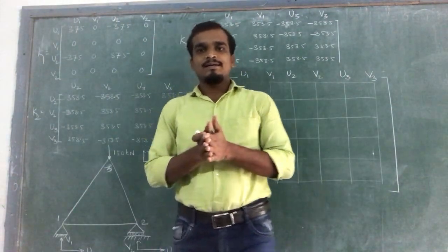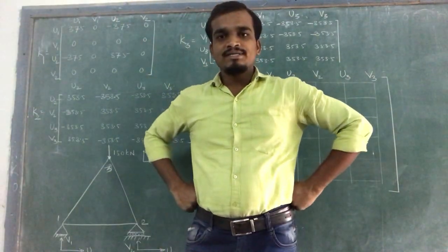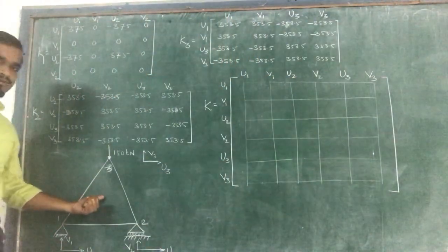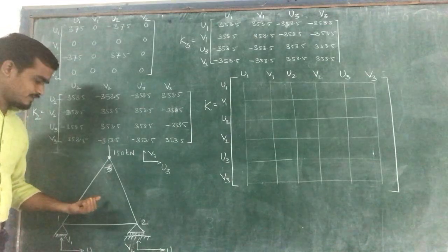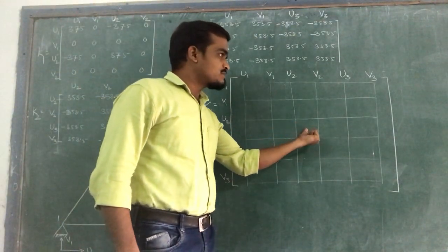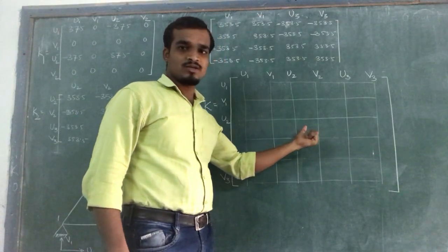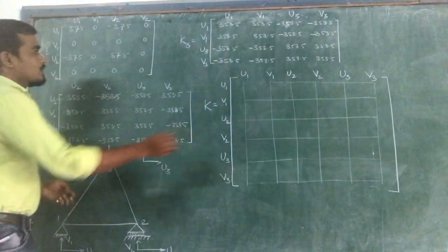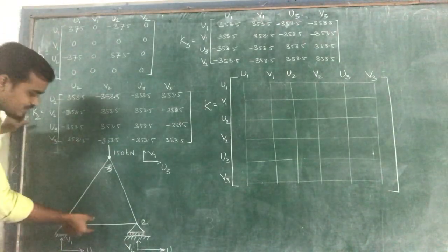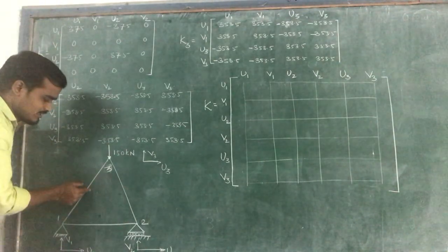Good morning, guys. In the previous lecture we started our truss problem. We started this problem in the previous lecture. Now in this lecture we will construct our global stiffness matrix for this truss element. In the previous lecture we determined our elemental stiffness matrices for the first element, second element and third element.